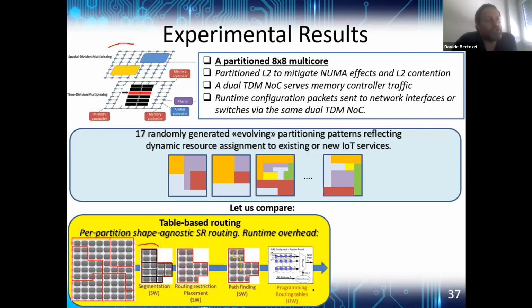There are other approaches that do not use tables, but they are not strictly aiming at shortest path routing. Even in case shortest path routing is possible, they end up taking non-minimal, suboptimal paths. So it's actually a trade-off. LBDR doesn't take this approach. It prefers to limit flexibility a little bit, but to always try to take the shortest path route to the destination.